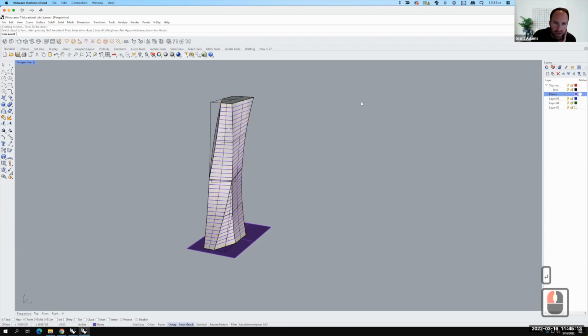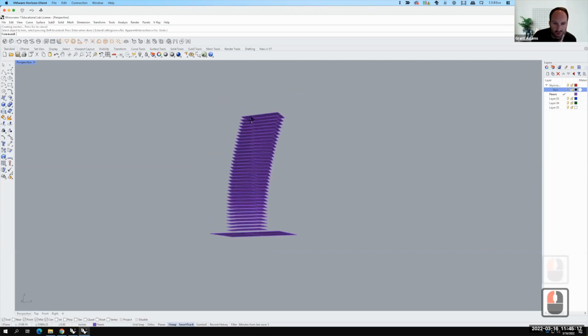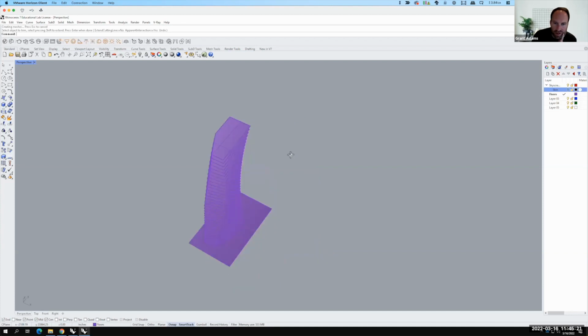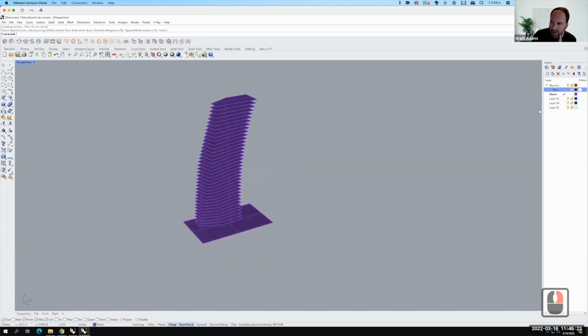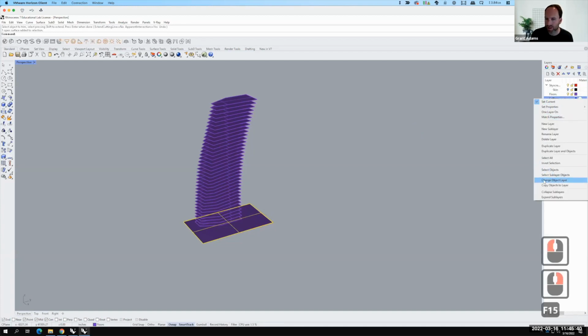And you can see that if I were to turn off the skin layer, I have all of those floors, and they've been trimmed to fit inside of the skin. So that's good. Next up, we need our ceilings on each of these floors. We'll type in ceilings. We'll make it active. Let's change this into our ceilings. So let's right click, change object layer.